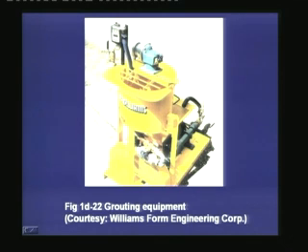In this mixing unit, water and cement and any other admixtures like water reducing admixture, expansive agents or pozzolans can be mixed, and after the proper mixing, the pump will push the grout material through the tube, and this tube is attached to the grout hole in the bearing plate of the anchorage block, and through that the grout is pushed till it fills the complete annular space between the steel and the duct.